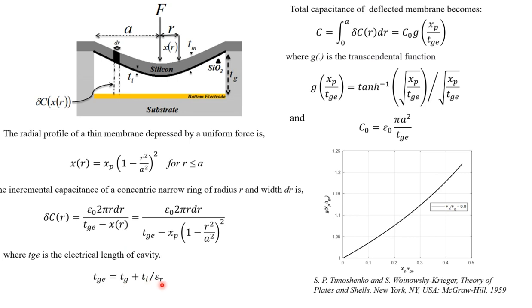So materials like hafnium oxide or aluminum oxide, for very thin passive films which have been deposited by, let's say, ALD processes, in terms of having very thin nanometer thickness films, the effective gap height is also, you can say, just Tg, because permittivity for materials like aluminum oxide is 10, hafnium oxide goes to 20, and it is in nanometers, so the second term could be a very small quantity. But if materials like silicon dioxide having lower permittivity like 3.9 or 4, then you have to add this to Tg.